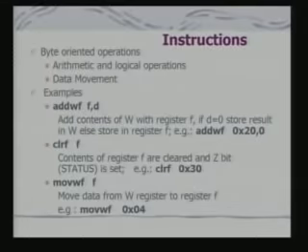There are a variety of instructions in PIC. Although I have already told you this number of instructions is much smaller compared to that of a typical CISC processor. If you are familiar with 8086 or 8085, you will find that compared to 8086, the number of instructions here is much less. And what is more interesting to note is the addressing modes. The number of addressing modes that are supported is also much less compared to any CISC processor.